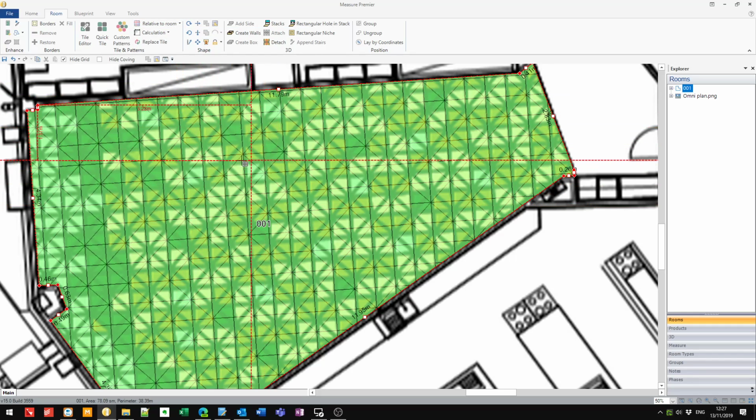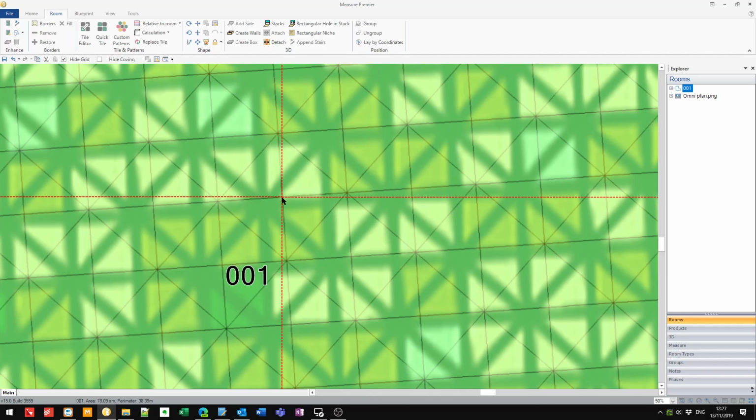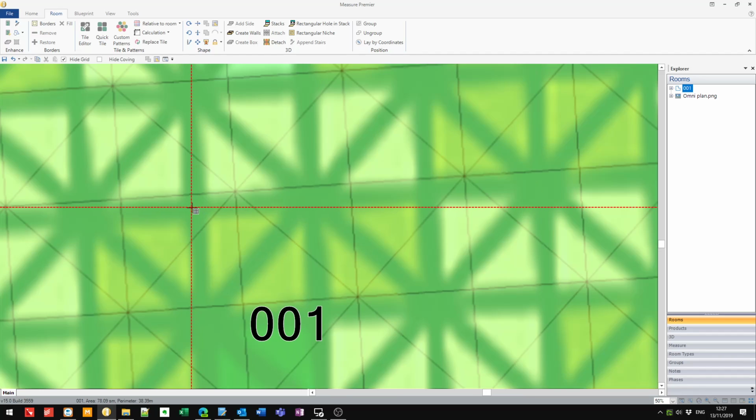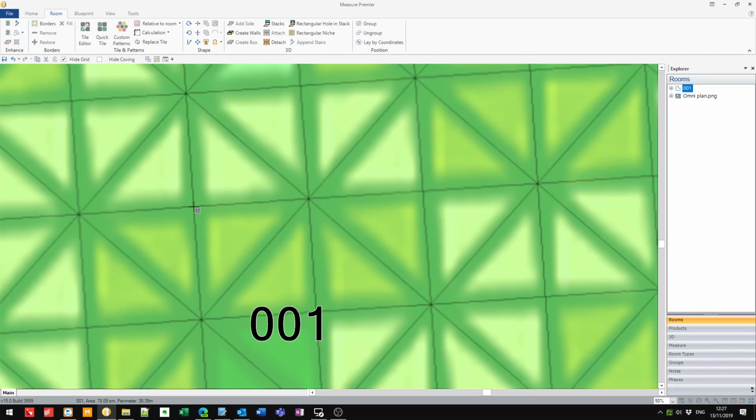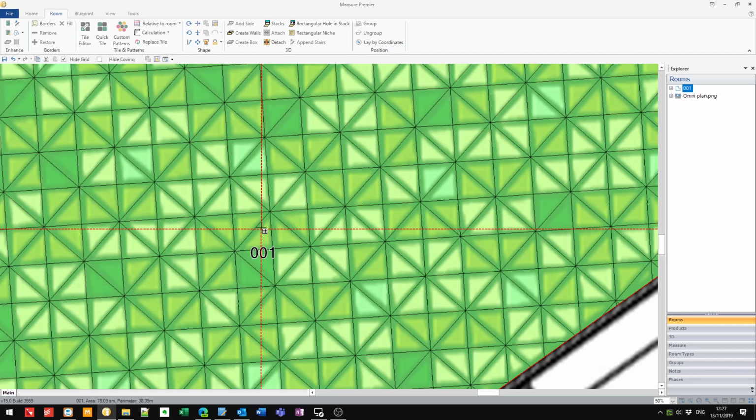When you do that, you'll get a crosshair that appears, and this lets you choose where the pattern begins. Now, initially you want to just click somewhere and observe which part of the pattern is moved to that spot. And then based on what happens, you then can move to the right part of the underlying PDF's pattern and click in the right spot so that the pattern grid lines up with the tiles you've got, or the colored tile pattern you've got on your PDF.